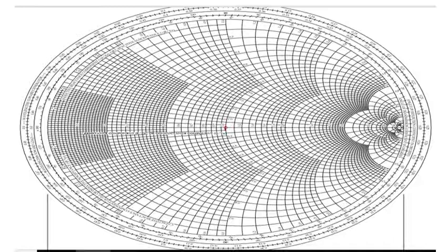So this 2 circle, I'll just highlight it. It's not required. We just have to find the value. It's just for your reference. I'm just highlighting this circle. This is the circle I'm interested in. I just have to find where is plus j1.6. So where do you find impedance values? It is always inside. So this is my 1, this is 1.2, this is 1.4, this is 1.6. So you can see this is going down. I will not highlight it, just for your purpose I'm doing it. Otherwise we don't do this. We just take that point.